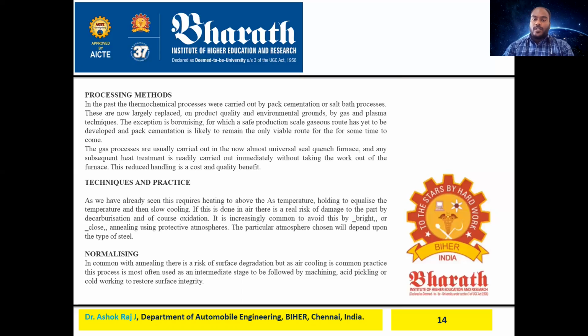The gas processes are usually carried out in the now almost universal sealed quench furnace, and any subsequent heat treatments are readily carried out immediately without taking the work out of the furnace. This reduces the handling and the cost, as well as giving a quality benefit.